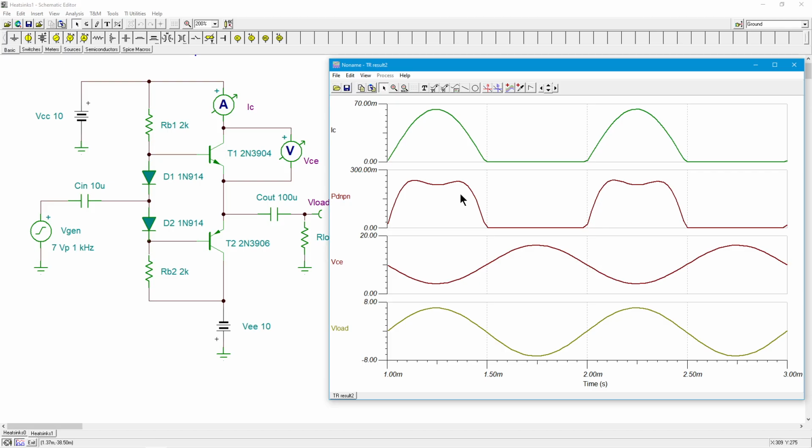Now, the true power of the transistor, of course, isn't this as far as the heating of the transistor goes, because there is a thermal time constant. Just like if you take a saute pan and you put it on the stove, it doesn't heat up the instant you put it on there and cool down the instant you take it off. There's a thermal time constant, same thing like an RC time constant. It takes a while. So what ends up happening is this just averages out. We would find the area under the curve and average that over a full cycle and see what we come up with, right? So again, that proof is in the textbook.